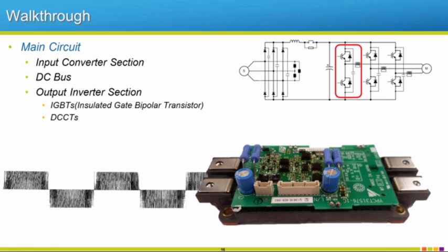So we have a very high DC bus voltage. And I don't think I mentioned it before, but you can always do a quick calculation to figure out what kind of DC bus voltage you have: whatever your incoming voltage is, times the square root of 2, and that will be your DC bus voltage. So we have these freewheeling diodes that allow us to regen back into these capacitors during a decel. There are different ways to mitigate that issue. You can use resistors to burn off excess energy. You can use one of our RC5s, DC5s to regen back on the line that way. You could add excess capacitors, or if you have another drive, you could do common busing between the drives. There's a bunch of different possibilities to get out of that overvoltage scenario, or just increase your decel time. That's the simplest way.